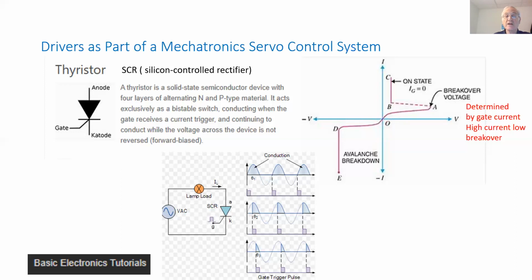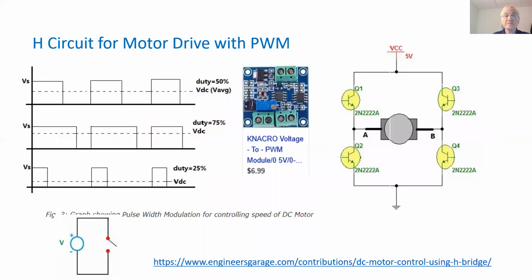So this is when the light is on. When we pulse it over here, the complete half sine can activate the load, and when we apply the pulse over here, then only a quarter of it, and over here we get a smaller portion of it. So that's how we may use it in a rectification circuit.